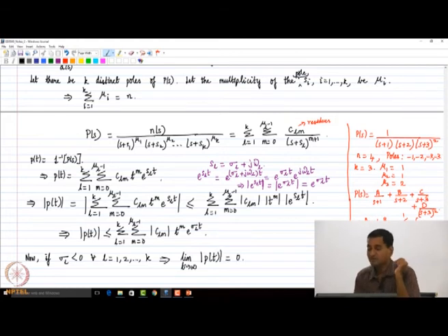Now immediately one may ask, what about the t power m term? It so happens that the exponential term with the negative exponent will dominate the t power m term. So the product will go to 0 anyway. So it turns out that the sufficient condition for the impulse response to asymptotically go to 0 is that all poles have negative real parts.